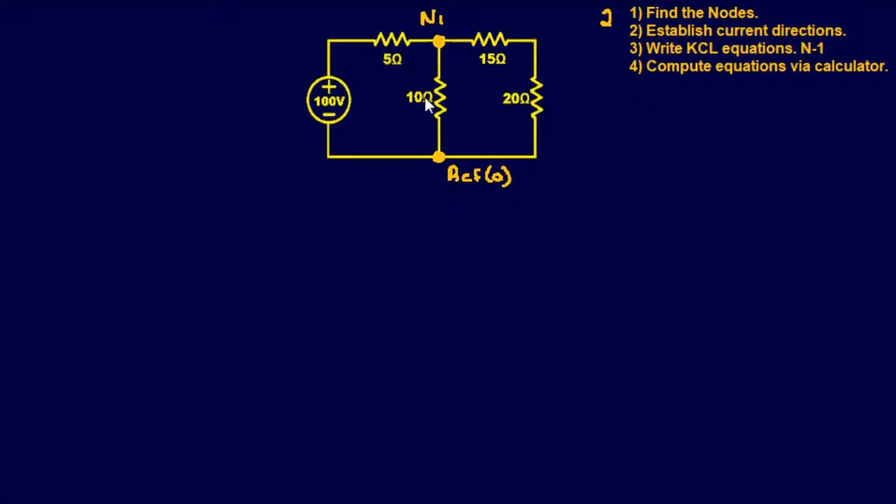This is where you guess. You don't have to get it correct every time, as long as you follow the rules. It must have a minimum of 1 output and 1 input. So I'm going to say current's flow in this direction, and that direction. Same thing with this node. I'm going to say it's going in that way and back down that way. Seems logical, right?